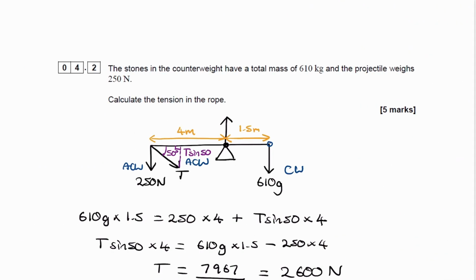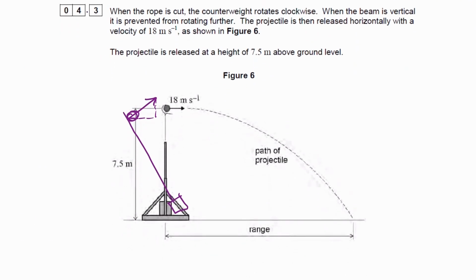But if we go back to the diagram, the mass down here is not going down all the way to the lowest position that it could, in which case we're not losing the same amount of GPE as we would if the beam were vertical. If we're not losing the same GPE, then this mass is not gaining the same kinetic energy in the end, so its horizontal velocity at launch would be lower.